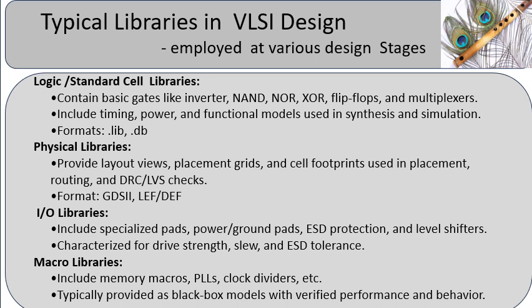I/O libraries include specialized pads, power and ground pads, ESD protection, and level shifters, characterized for drive strength, slew, and ESD tolerance. Macro libraries include memory macros, PLLs, clock dividers, etc., typically provided as black box models with verified performance and behavior.